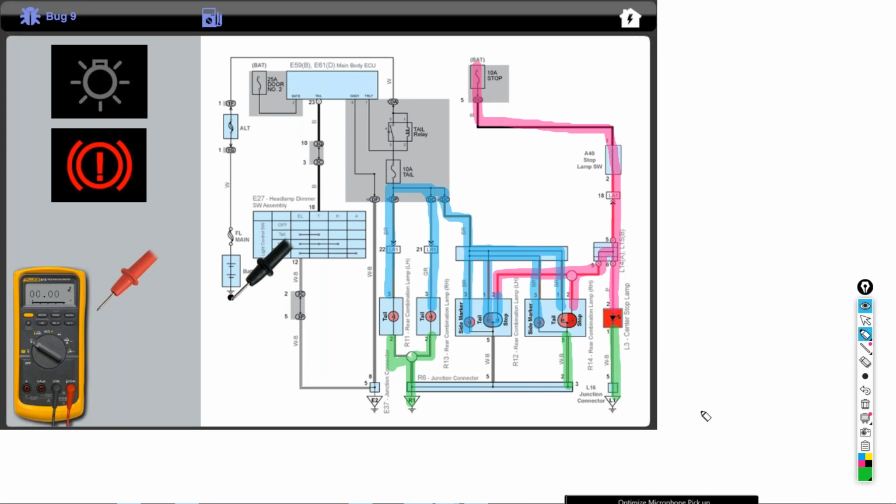So I've actually worked on several cars and pickups and stuff like this. A lot of them when the owner had put their own trailer light wires in there and cut the ground for one side or the other. So this helps to demonstrate how current flows and how you can get a feedback by a ground. So bad ground can create a feedback. One circuit feeds into another circuit. And so you step on the stop lights and the park lights come on. I've even seen stuff like that. The dash lights come on since they're tied into the park lights many times.